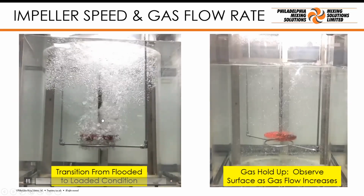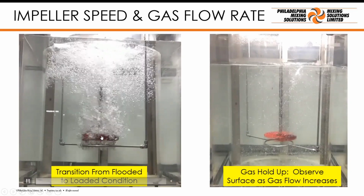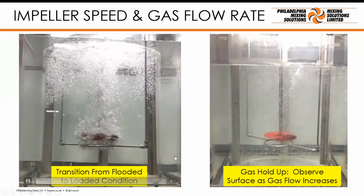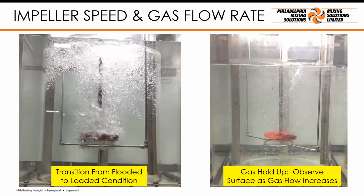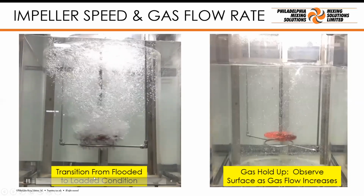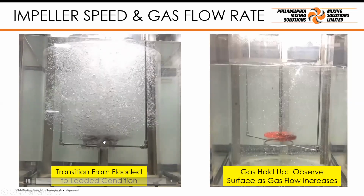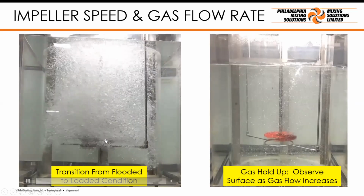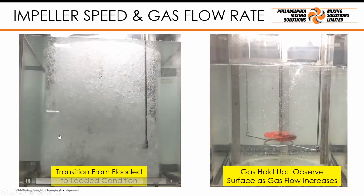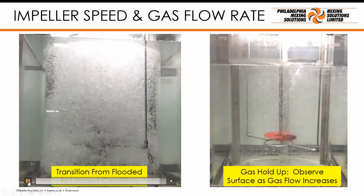So we're going to talk about the transition from flooded to loaded. When the agitator's running at low speed, the buoyancy just allows the bubbles to pass through the impeller and rise up to the liquid surface. As we increase the impeller speed, the inertia in the fluid flow can take hold of the bubbles, overcome the buoyancy, ultimately drive the bubbles out towards the wall of the tank, and then recirculate the bubbles underneath the impeller.